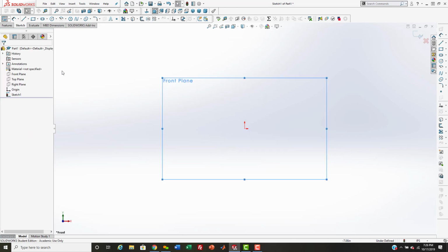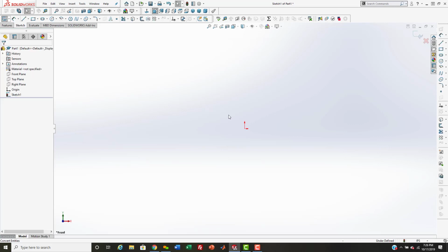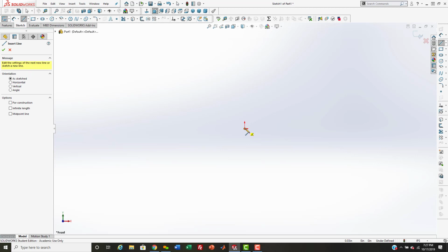So let's remove all that. We're still in our sketch. Now, if you hold down the right mouse button and move your cursor, the mouse, it brings up this circle of commands. Here you have your square, your fillet, the circle, sketch, drawings. Okay, once you cross into it, it will automatically go into that command. So align and trim. Now you'll see here that I've got 8 commands available to me. So let's just do a draw line here.